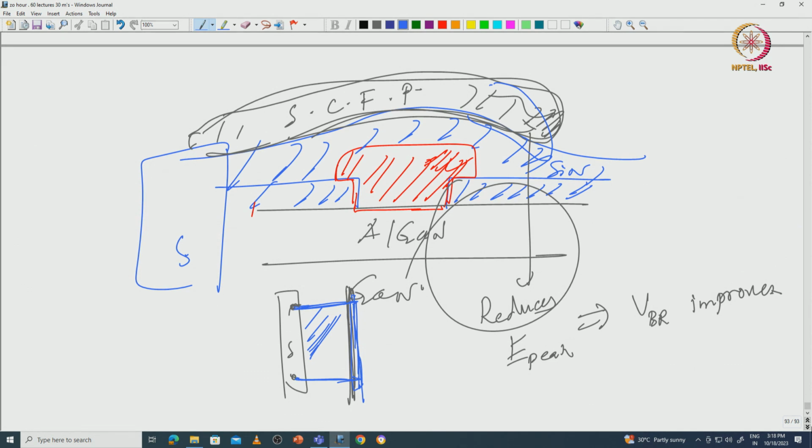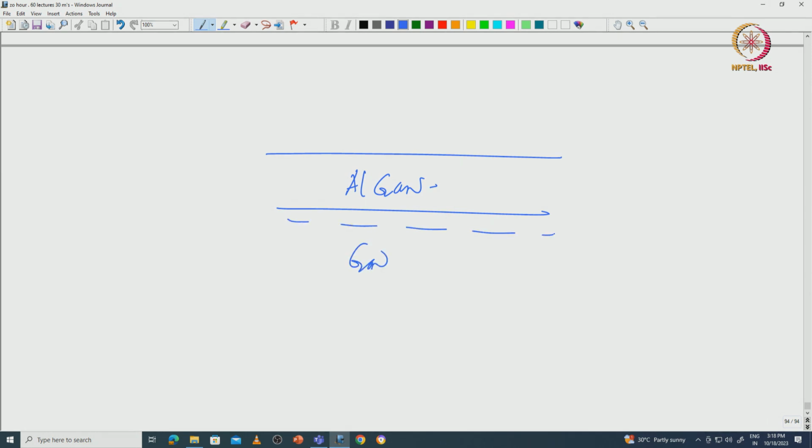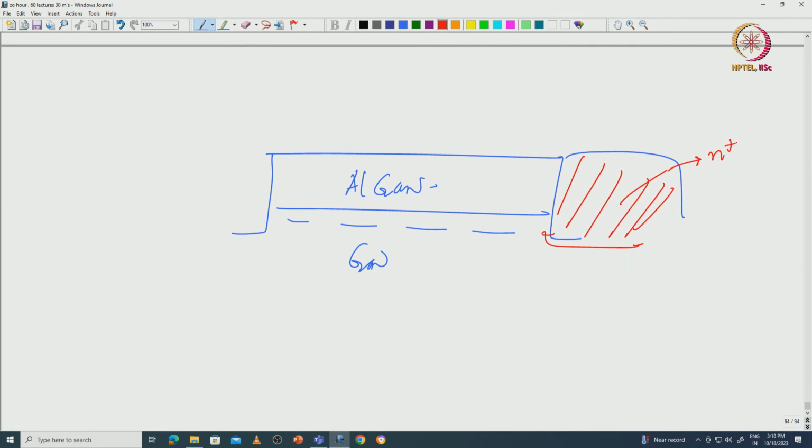When I say regrowth, I mean, to get to really low contact resistances, if you have AlGaN here, and this is GaN, what people do is that they etch away this part in plasma, and then they put the material back inside the MOCVD or MBE, and they grow this part with extremely highly doped N plus gallium nitride.